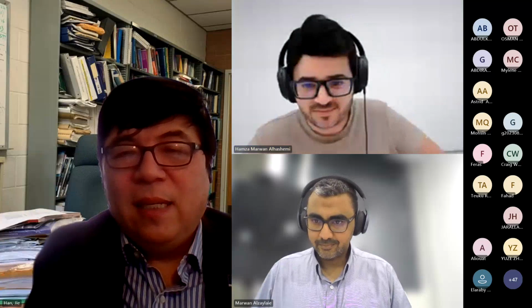Ahmed Awad is back to the isolated footings question on stone columns. He said they have done testing in between the columns, but they found out the soil is not improved. So do you recommend anything in such cases? Yeah, as I mentioned, this is referred to soil. It's not a composite, right? For soil, if the soil is clay, you will not get improvement. That has nothing to do with the isolated footing or the mat foundation, same thing. But if you talk about the composite, you should get an improvement. If there's no improvement, that's a problem with installation or whatever.